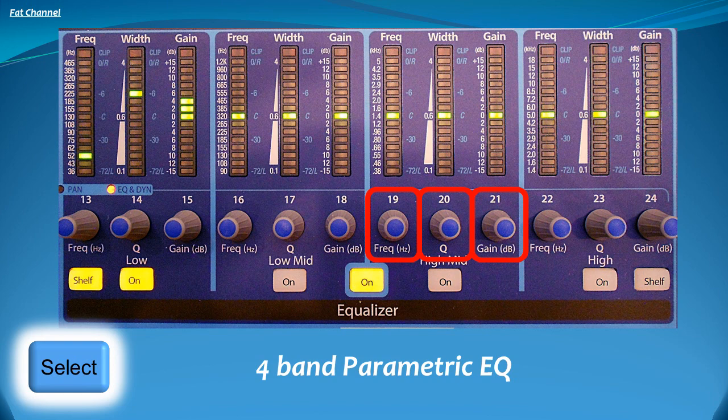Here are some EQ concepts worth remembering. Positive gain is also known as boost. Negative gain is also referred to as cut or attenuation. The term bandwidth here refers to a range of frequencies. A higher bandwidth covers a wider range of frequencies and vice versa. Q is the measure of the width of the frequency band being affected. Q is inversely related to bandwidth. The higher the Q value, the more narrow the affected bandwidth, and vice versa.